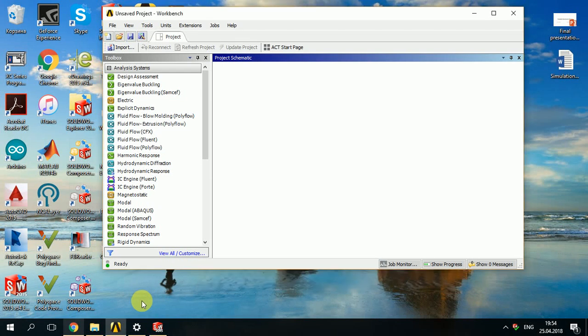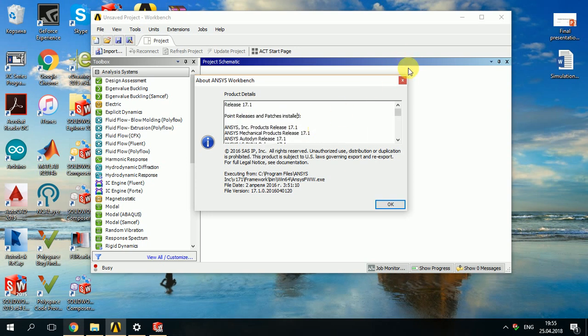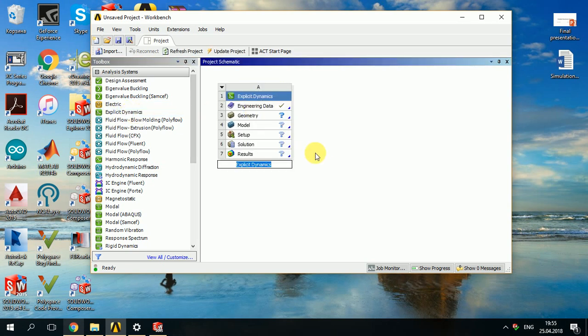Hello everyone, in this video I will show you how to set up a simulation in ANSYS Explicit Dynamics. So here you can see the Workbench, and I use a version of the ANSYS Workbench. In order to start the setup, I need to select Explicit Dynamics. First of all, I need to select engineering data.